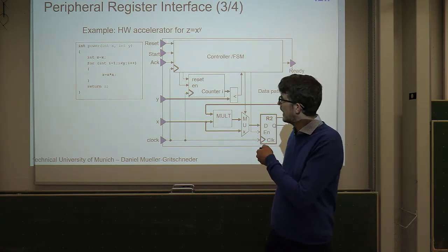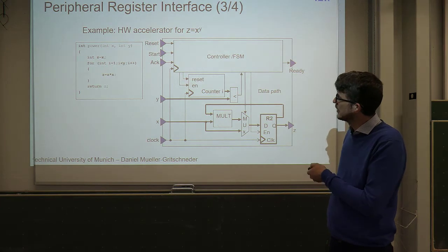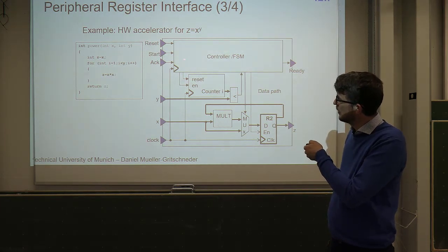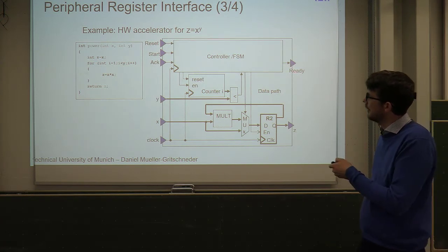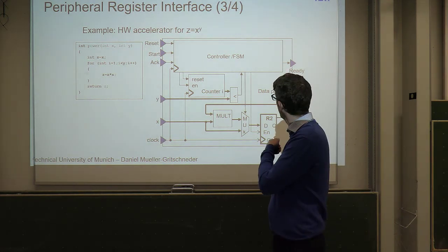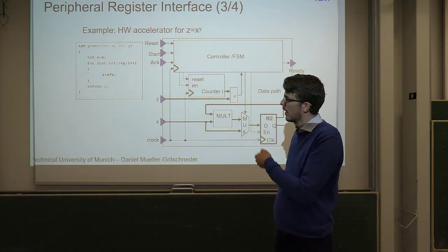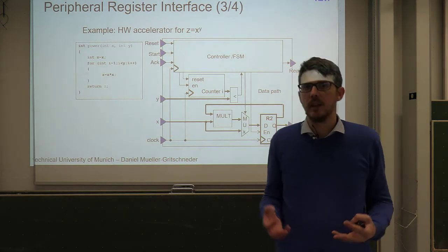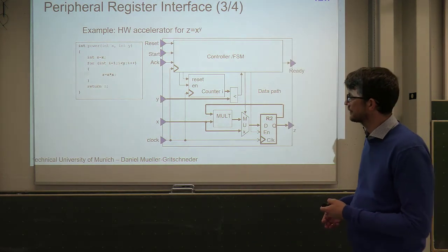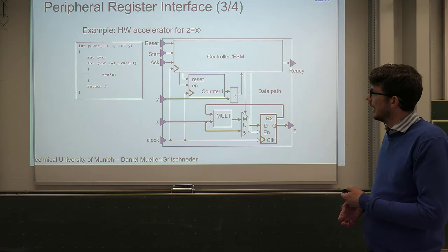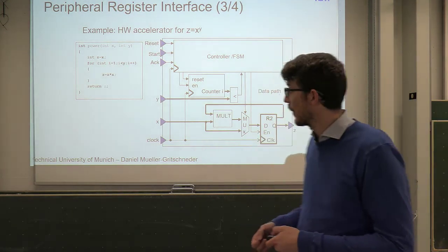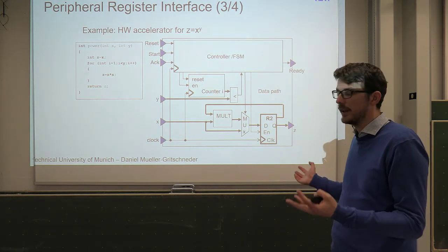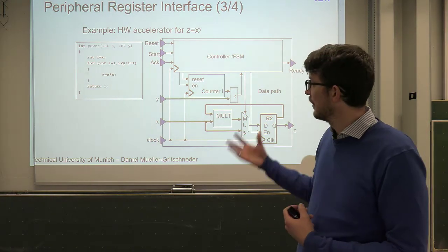Then you also need some handshaking, so you have to be able to reset this module. You have to tell it when to start the computation. Then it has to report to you when the computation has finished, so when the result is ready. And then, for example, after it has finished you can give an acknowledge and say, now I have read the value, now you can do the next computation. If you are a programmer and have done some Verilog or VHDL programming, I'm very sure you're able to design this hardware and it would work.